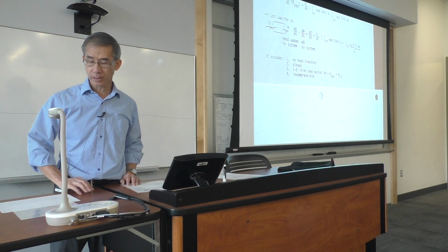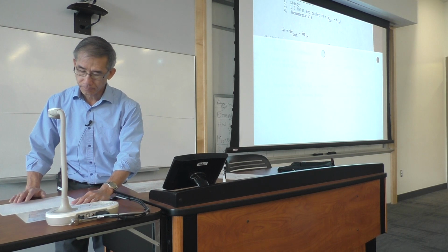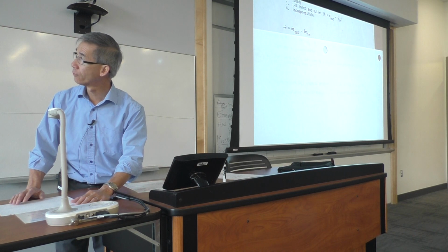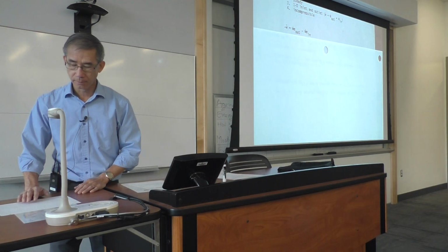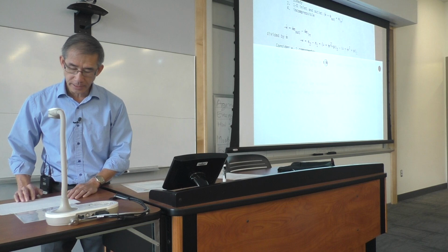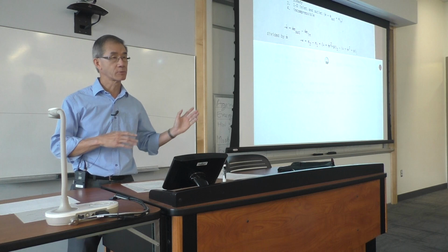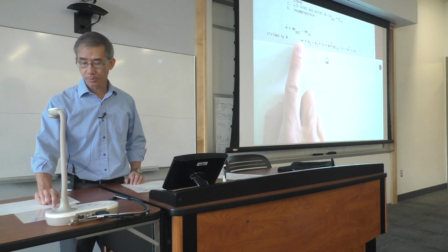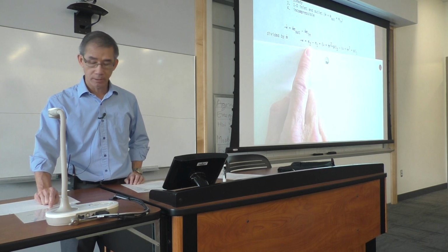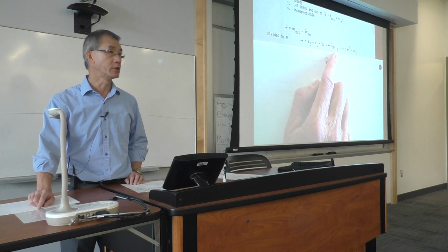And throw in the incompressible assumption of constant density, the equation now becomes the first law for a control volume, which can now be written as this, where the heat transfer Q disappears and the work is now per unit mass. From my Reynolds transport equation, all this is equal to the change in total energy.